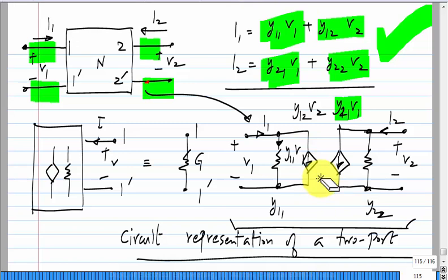Yeah. So, that is right, I mean if we do connect it, it will become 3 terminals, but in the actual circuit this and that may not be connected, or if you connect it, let us say for instance you have a resistance here between these two, okay, and if you connect it, it shorts out the resistance. Okay. So, that is why actually I do not like this kind of description too much, but because it is used very commonly, I will use that. So, in reality, for a 2 port you should have 3 terminals, right. With 4 terminals you should legitimately define a 3 port.